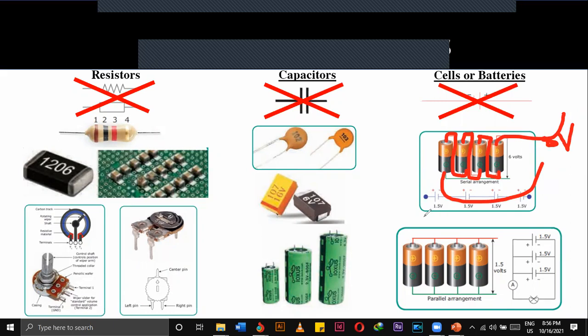Similarly, if you connect like this, particularly this one, take positive and connect it to positive. Then take another wire, join together, and make it positive. Then join a wire to this one and make it positive. If you connect like this, the voltage between these two terminals will be the same, 2 volts. That means if it is a 2 volt battery, this one is 2, this one is 2, this one is 2, and finally the voltage will also be 2 volts.